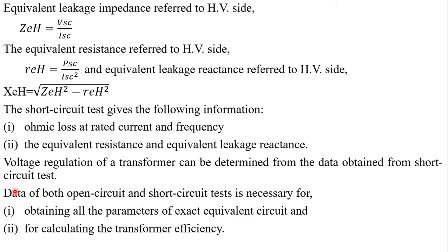Now, the data of the open circuit and short circuit tests is necessary for obtaining all the parameters of the equivalent circuit, which is used to determine R1, X1, R2, X2, RC, and XM, and also for calculating the transformer efficiency, and for calculating core loss and ohmic loss.